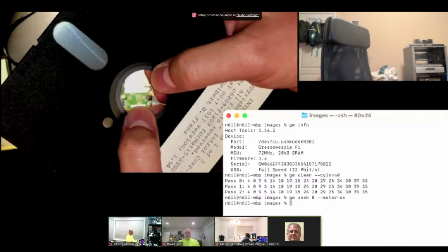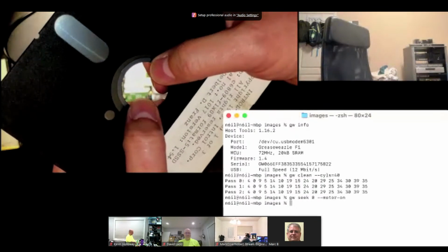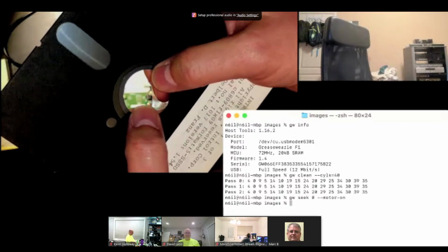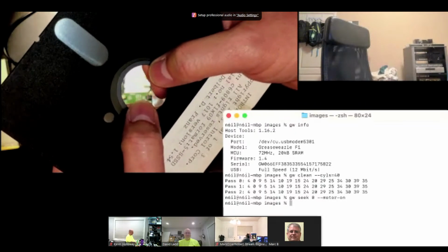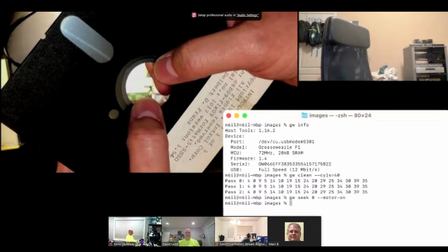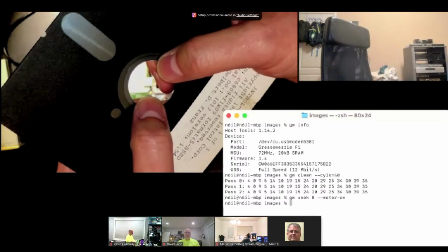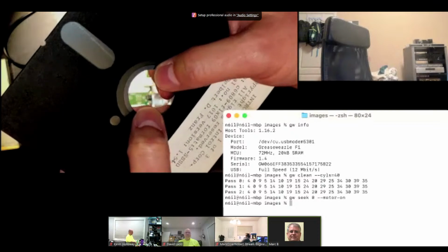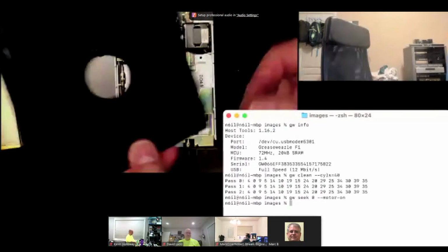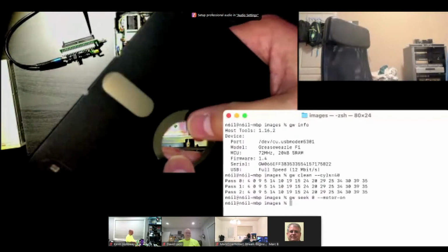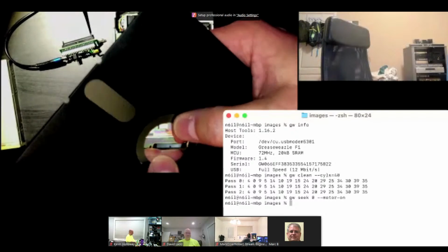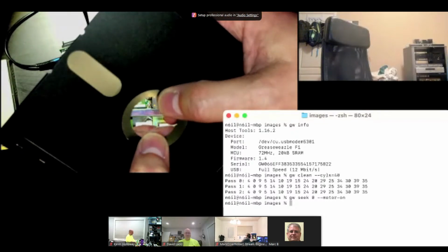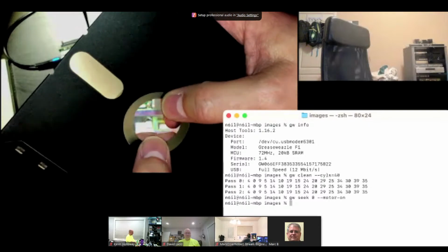If you want to get a good image, you can see a little bit of scoring actually. Can you guys see that? If I turn this back and forth a little bit, you can see there's a little bit of scoring on this disk. Well, it's not that bad. Well, if it gets to looking like a record, you're in trouble. Yeah. So that's this side of the disk. The disk is turning freely in here. It's not stuck. It doesn't seem like there's any junk.